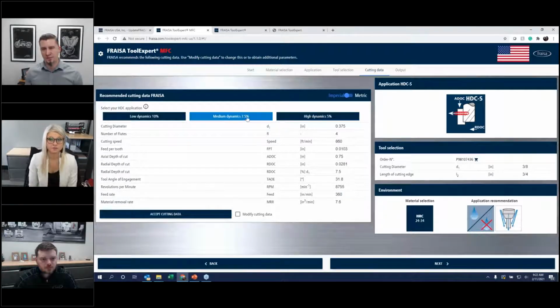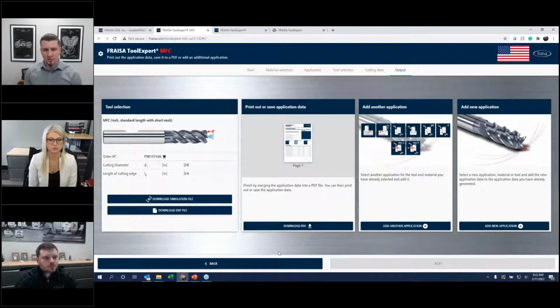So you see, if we went from 5 to 7.5%, our metal removal rate stays the same, but our feed rate dropped to 360. If the machine wasn't hitting that 80% of the time, then we would drop it even further to 10%, which is 271. So the key factor there, just make sure that it is giving you the 80% of the time reaching that actual programmed feed rate. So we got our speeds and feeds here. Let's take a look at this tool in action.